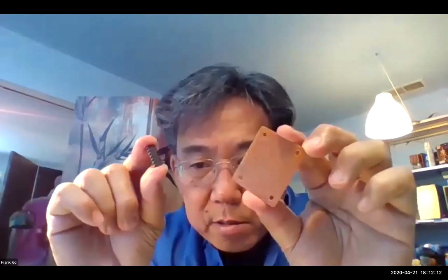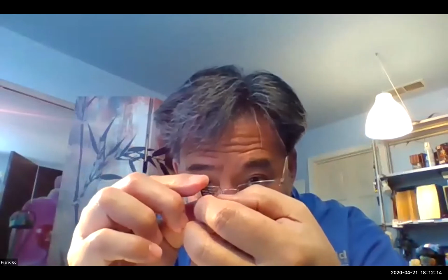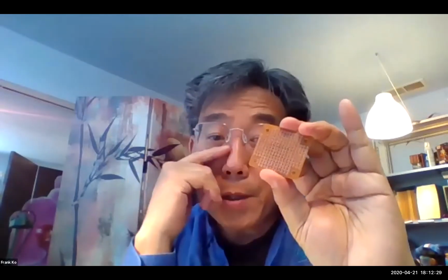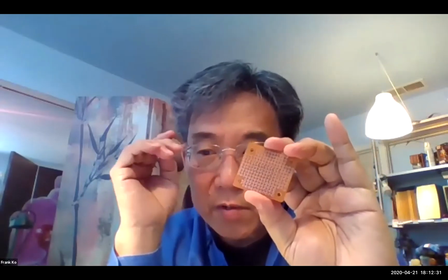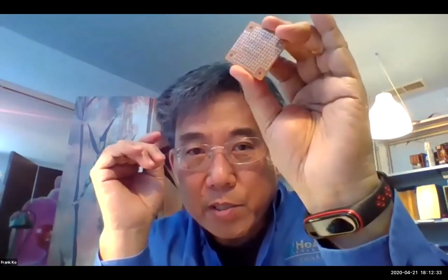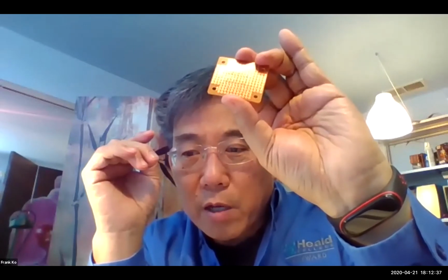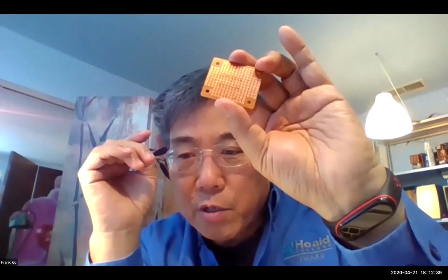But as we move on to next week, Nabil, if you could remember, on this particular kit, this is 1, 2, 3, 4, 5. So it's a 14-pin chip. I would strongly encourage us to provide the students with a 14-pin socket. This way, they're not soldering directly onto the 14 pins of the chip itself. So if you could remember to include that, Nabil, I would appreciate that very much.